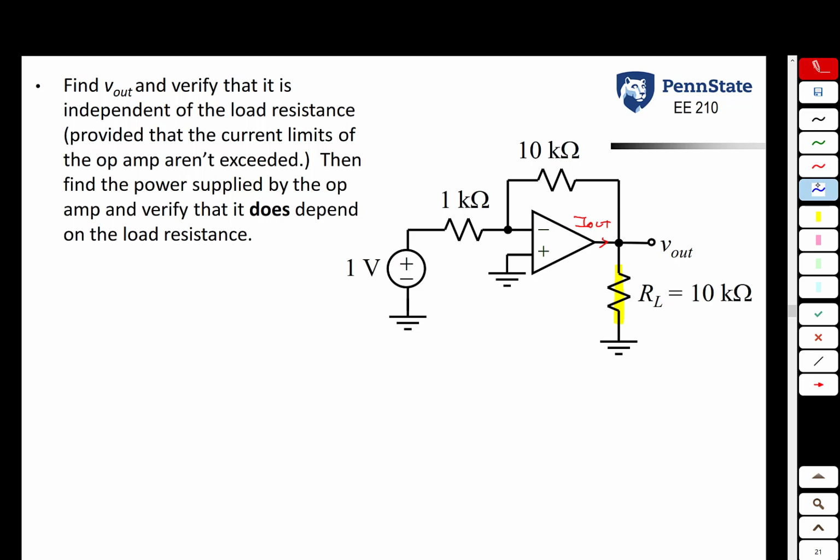So let's solve this circuit. Once again, this is an inverting amplifier. So the way you analyze it, you first find the voltage at the non-inverting terminal. We get that from inspection. It's 0 volts. And because of the virtual short circuit approximation, the voltage at the inverting terminal is also 0 volts. The next step is we do KCL at the inverting input terminal.